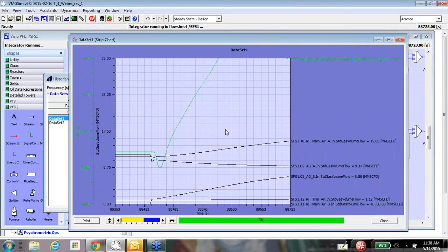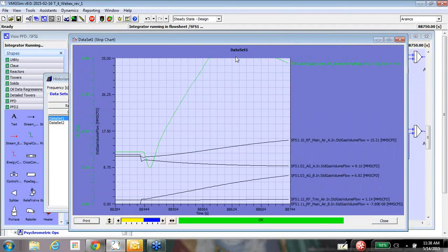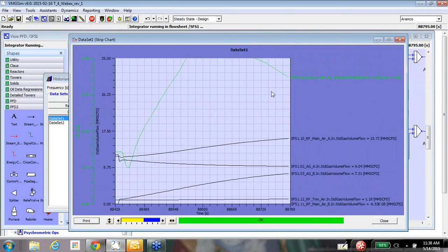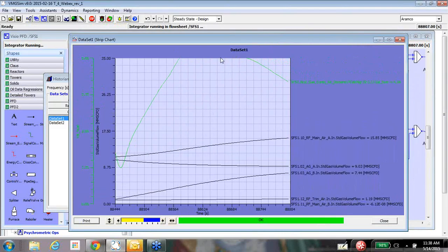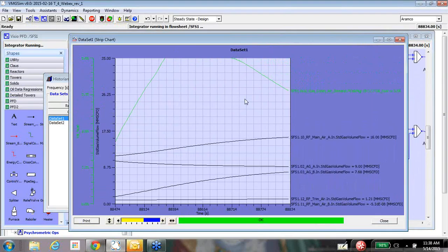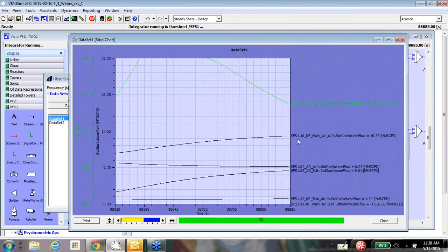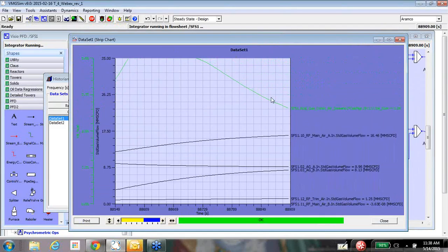So here you can see at a certain point the ratio exceeded a certain amount like 5, but when you are studying different scenarios, you want to make sure what step change you should go with, because this will give you a little bit of help on how far off your ratio is really going, because if your ratio is really too far off, it could create a sulfur fire in the plant or in the pipings. So you've got to make sure what step change you should go with, and you can study all those things from the strip chart as well.